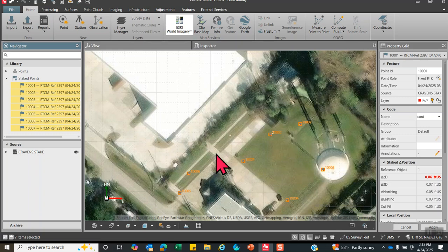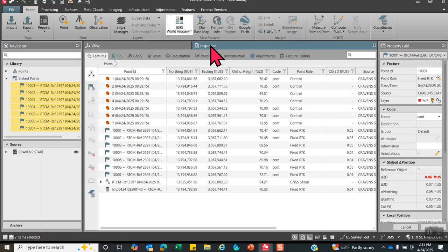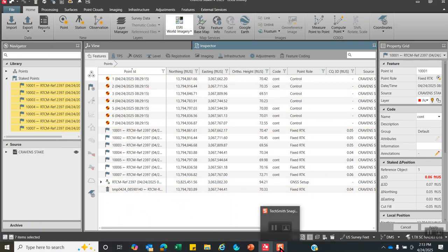So once again, Infinity is real handy, creates nice reports, pull the data in. We're in Texas South Central. If for some reason that was a wrong coordinate system, then we can change it right in here as well. Okay, and here's all the icons, the base station, and any point that was deleted, we can recover those points. And we see the points we uploaded, points we staked, and everything's in here. So hopefully that helped out.